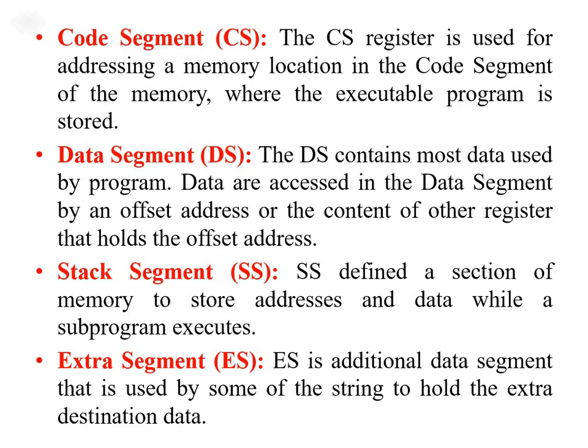Next is the extra segment. This is an additional data segment that is used by some of the string instructions to hold the extra destination data. Basically, we are going to use this extra segment in one of our assignments related to string operations. That means whenever you are taking input from the user as strings, you will be using the extra segment.